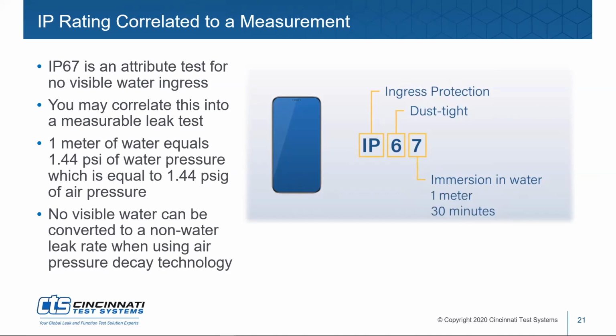It's kind of interesting. Lots of the IP67 products are things like phones, watches, or enclosures, because that's where this spec comes from. So a sealed enclosure sometimes has a port where our customers will pressurize internally or pull vacuum internally and look for a pressure decay leak. But for those that don't, you actually have to put your part in a chamber and do what we call a sealed part leak test, using a test chamber with a starting volume of pressurized air that equalizes to that chamber. And you test first that the equalization comes to a specific measurement, because a sealed part could have a gross hole in it, and if you just pressurize it with a regulator, you will pressurize the inside of the part and the outside chamber and never test for a leak because the whole thing's holding air pressure. Oh, so that's why you start with a known volume at a known pressure. Yes, exactly. Okay.